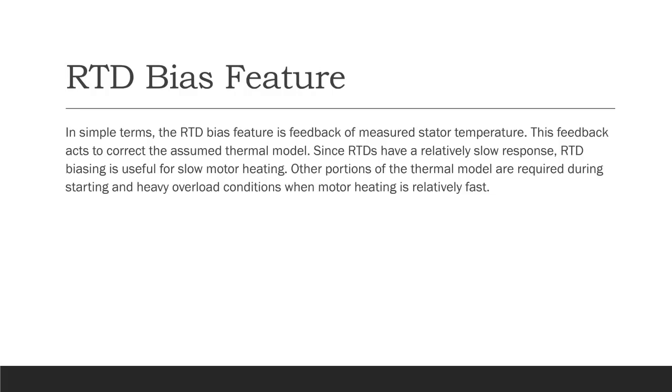One of the things I didn't mention, which has also happened, is when a motor gets rewound, occasionally the nameplate is not updated if it is rewound differently than the original nameplate. And that can also lead to an enormous inaccuracy inside of the motor thermal model.